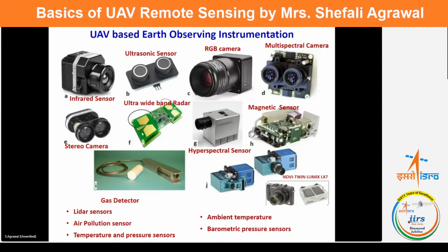But again, LiDAR payloads are slightly heavier and often flown with larger fixed wings for better stability in place of a quadcopter, in case of rotary platforms. But rotary platforms can also be utilized. But as I said, the weight of the payloads is slightly higher, because when you have a drone, you should also have another GPS module having an RTK or a PPK capability along with the LiDAR sensor.